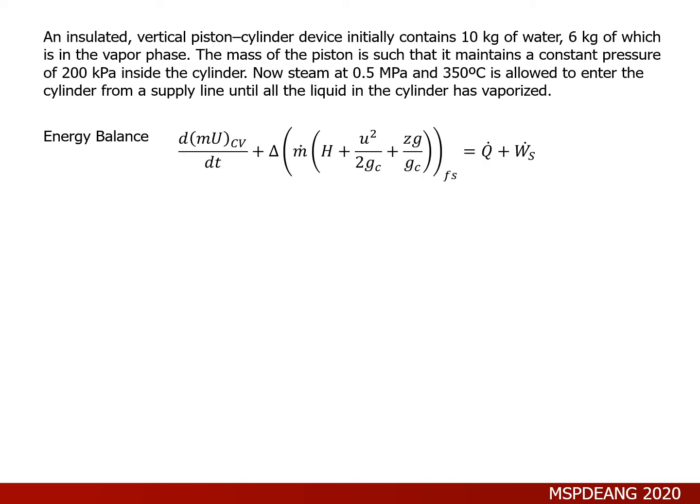So for the energy balance equation, again, here it is. Now, how do we simplify this further? So consider the steam supply again, steam going in, then initial and final conditions. We can approximate this scenario such that we can say that there is not much change in kinetic and potential energy, because the system did not move between the initial and the final. Okay? And our flow stream is only going in. So, we assume negligible change in potential and kinetic energy.